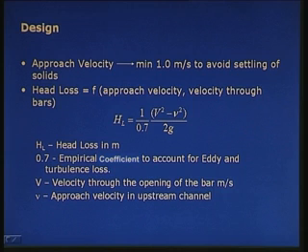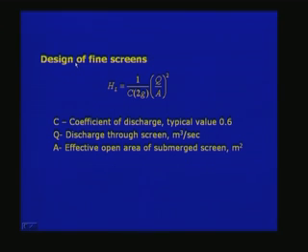Now, if you take the fine screens, then the head loss equation is given by HL = (1/0.7) × (1/2g) × (Q/A)², so this is the equation.